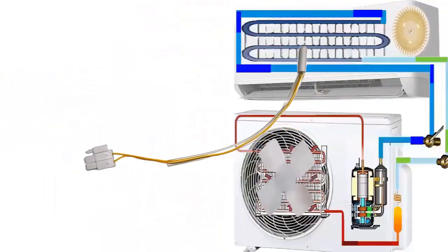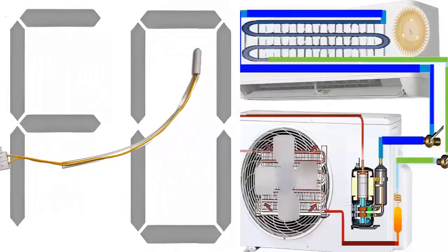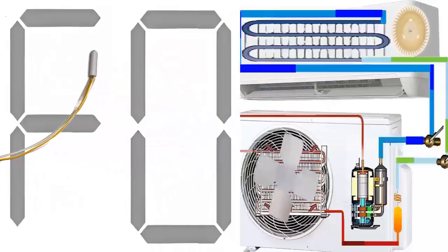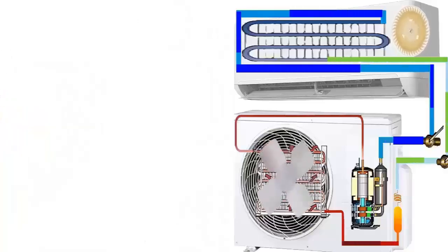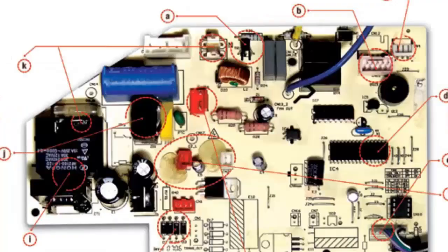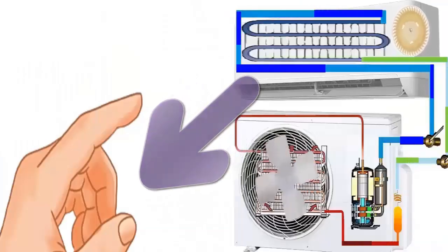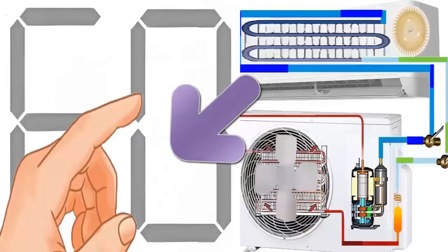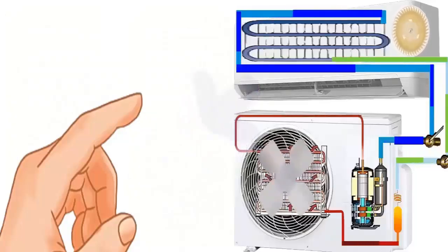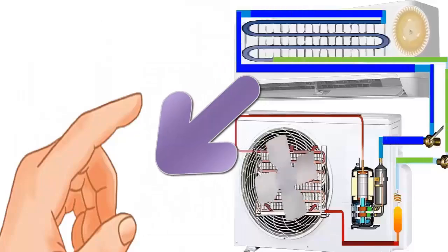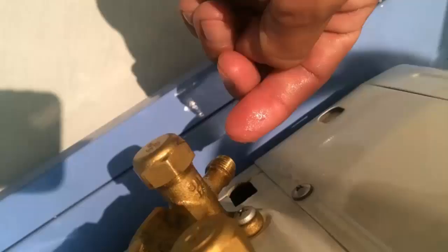9. If the error persists, consider replacing the sensor. If the problem continues, it may be related to the electronic board. 10. If the air in step 3 is not cold enough, there may be a refrigerant leak or cooling generation problems. Look for oil stains on the pipes that connect the indoor unit to the outdoor unit and on the coils, as oil often indicates leaks.